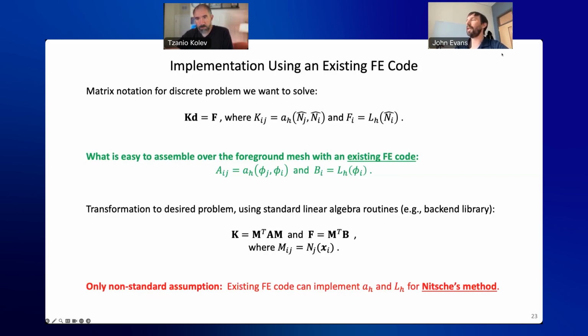But if you're interpolating onto the same foreground mesh, you can certainly do geometric multigrid with this approach as well. And do you expect AMG to work? That depends on the properties of M, for example. At a minimum, it needs to reproduce the near null space, so row sum 1, things like that.